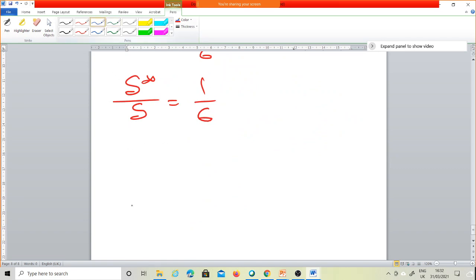And to calculate the drag, you know what you need. The drag is actually the integration of tau b dx, or you can write dA. So you need to know the tau in this case, right?